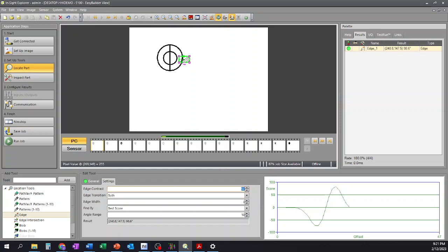And by the way, this search window is set right here within the program, so if this part drifts over here, this search window isn't going to see anything because the part is outside of its realm of understanding. The issue with using this edge tool with this particular part, by the way, even if we change our edge transition, what type it is, if we were to set this edge tool to all the way across this part, you can now see that it has caught every single edge in here.